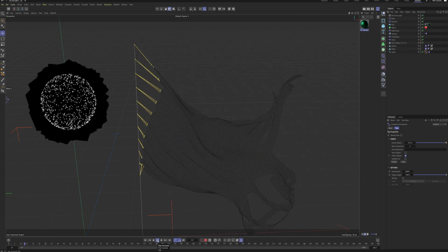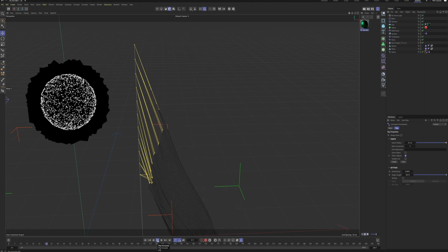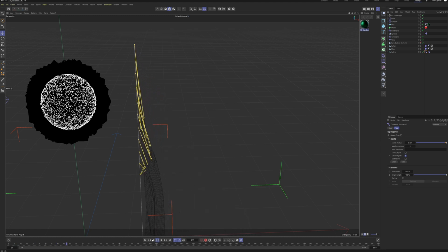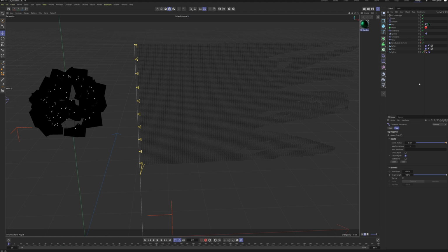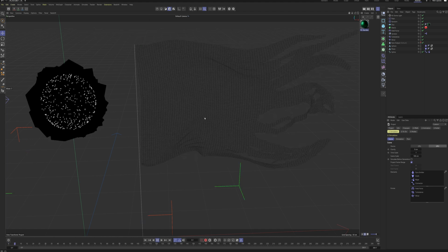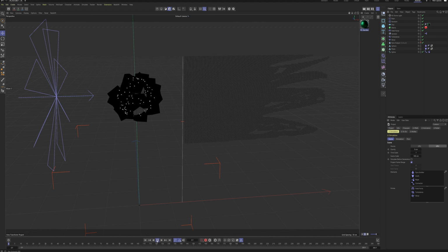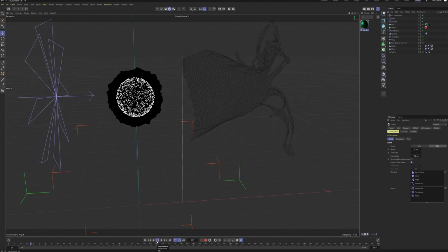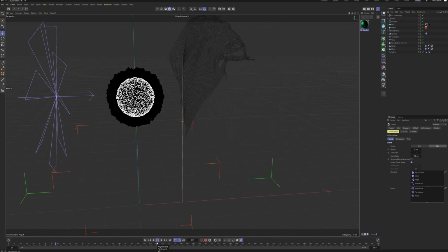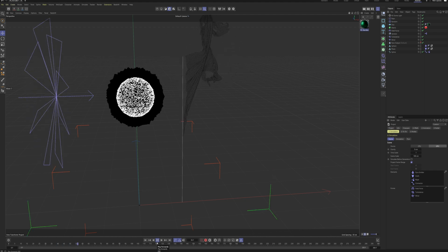But as you can see, we still have gravity on and it's really not that well connected. So what I want to do now is actually just go to my project settings, go under simulation, and I'm just going to turn off my gravity. And that should be awesome. So things are actually already animating here. And as you can see, it's a bit too wild.